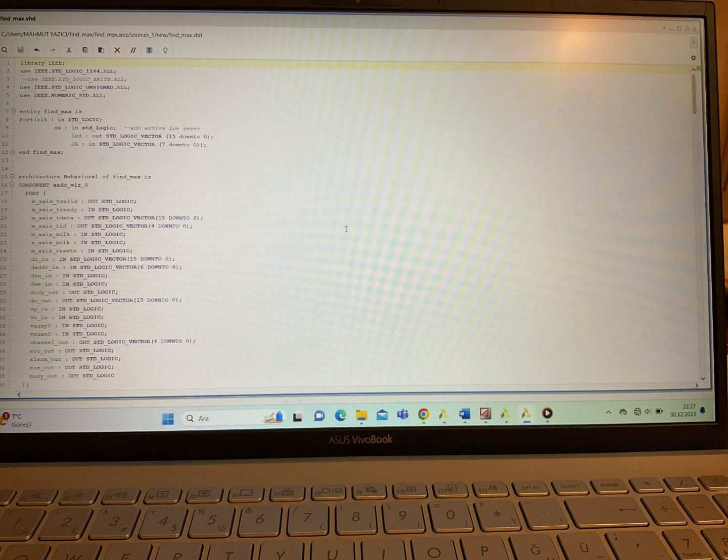We have the clock input, which is the 100 MHz internal clock of the Basys 3, and this clock is provided to both the XADC wizard and the FFT IP. We have the switch input, which is the active low reset for the ADC, and 2 bits of the JA input, JA4 and JA0, represent the positive and ground terminal of our incoming analog sound signal. Other bits of the JA are not used, and the most significant 12 bits of the LED are used to display different notes.